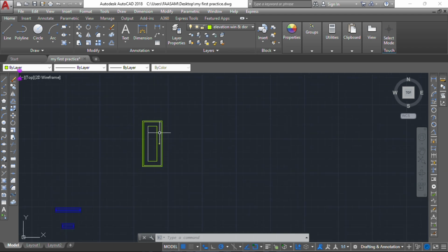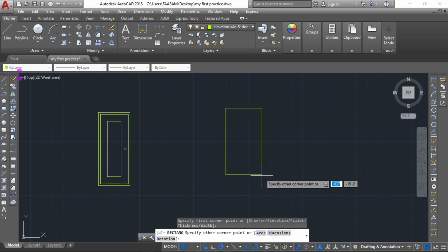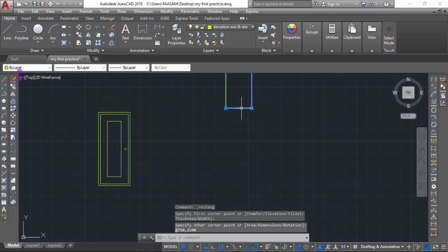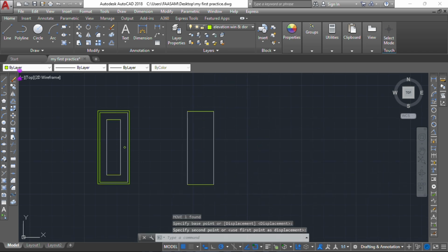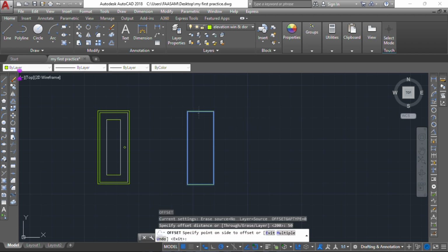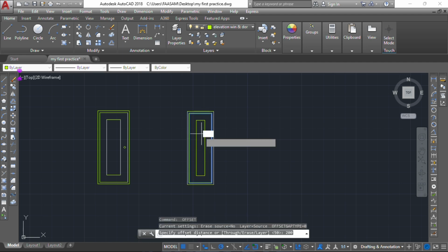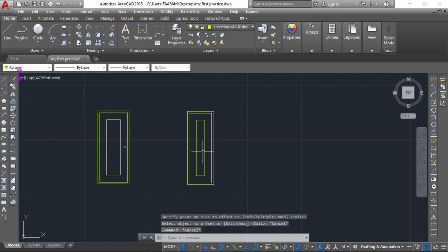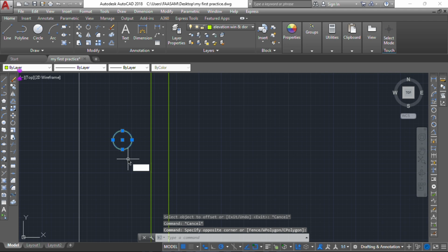for our internal door. Let's do the same for our toilet door, which is 750, I said earlier. So using the same rectangle tool, we're having 750, comma 21. Let's bring it down. Okay, so now let's use the same concept. Offset of 50, enter. Now let's offset this also of 200. Let's offset distance of 200. Yeah, this. So now instead of us creating another doorknob, let's just copy this.